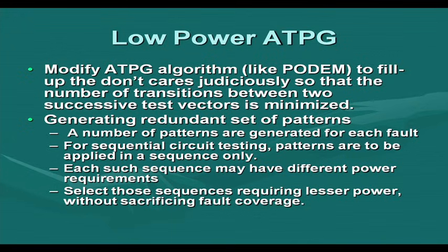Low power ATPG. Any standard ATPG algorithm will leave a number of don't cares not filled. Actually, those don't cares can be exploited so that we can minimize the transitions in a circuit.